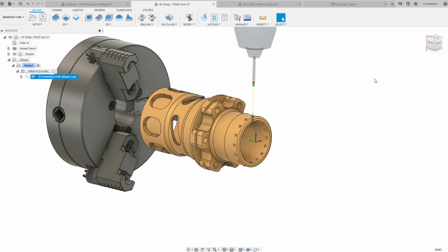And let's say it was a really long part, like it took up the whole X travel of your machine on a mill. You wouldn't want to go from left to right and then go back and maybe tap a ream or something, those holes from left to right again, because you're wasting machine motion. So you could reverse the pattern and you keep the same selections. So you select the first hole on the left and things like that. But now you have a pattern that will go from right to left.